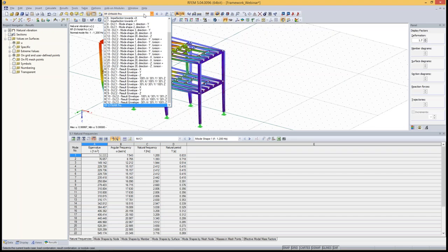And now we see that, first of all, you always know where the load cases are coming from. So there's always a note inside. This is the load case 8 is coming from dynamic load case 1 from the mode shape 1 in the direction 1. So it's always clear. The origin is always clear. And now in case of the dynamic load case 2, we have 2 load cases for mode shape 1 in the direction Y. So you get 2 load cases for each mode shape. One is in the torsion plus direction and the other one is in torsion minus direction.